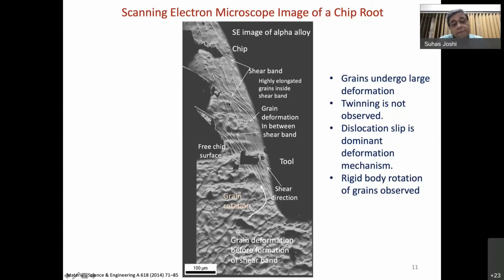But you can see that there are grains here. These grains are of similar size over here. There are grains here, of similar size to that, but there are lines here. These are the lines which show that the grains have got elongated in those directions.